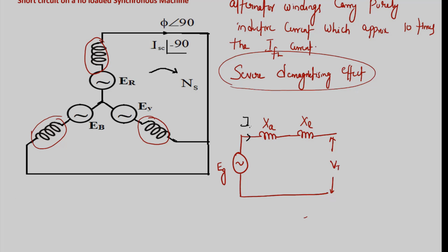Okay. There is no such physical reactance called XA. Because of the voltage drop that occurs due to demagnetizing effect, to model that voltage drop, we are keeping a reactance called armature reactance. Otherwise, there is no physical reactance. Why is leakage reactance coming? Because 100% rotor flux will not link with the stator. There is a leakage of 2 to 5%. To model that leakage, we are having this XL. So if you add both of them, it would become XT, that is XA plus XL.